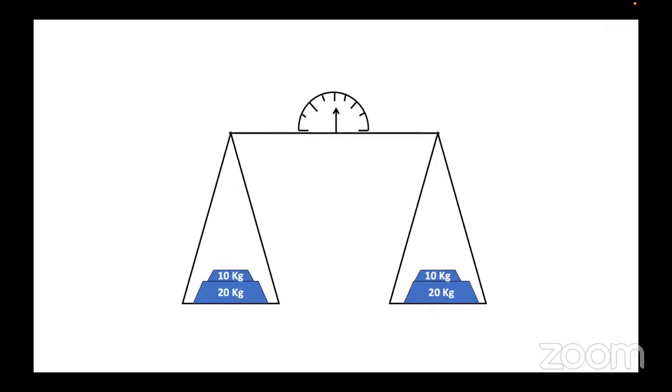That's what a Wheatstone bridge is. It's about balancing the resistances across. So whatever is being measured, depending on whether it increases or decreases, you will have to make corresponding changes in the variable resistance RV to maintain a balance. That's what a Wheatstone bridge is.